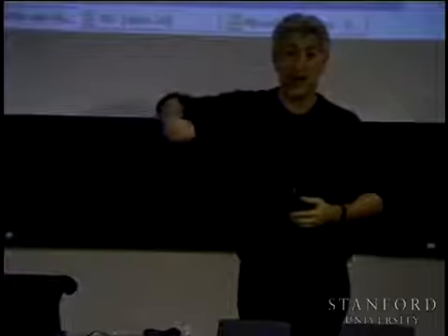You need to find a relationship between all these rigid bodies so that once the robot is standing, you know where the arm is positioned, where the hand is positioned, where the head is positioned. Well, I'm not talking now about sensors. We know the information, but we need to determine a model, the kinematic model.